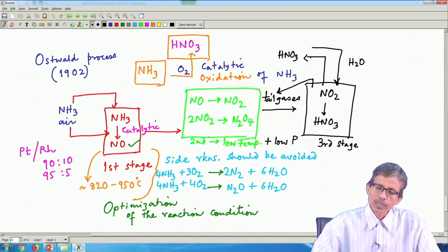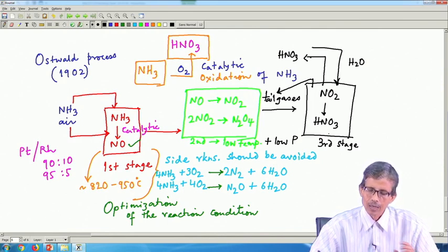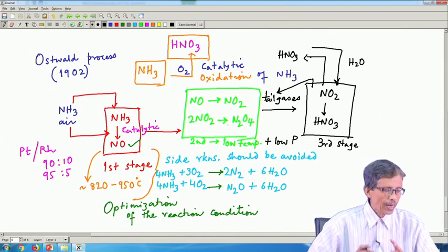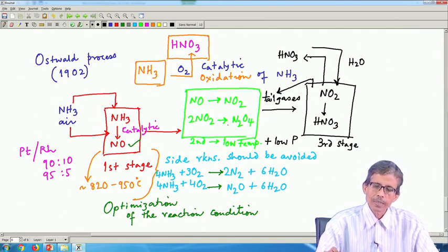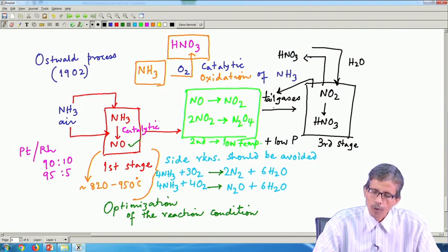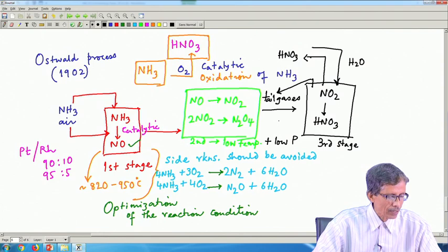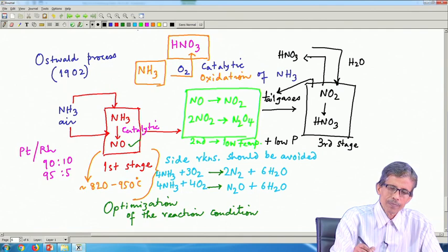So, the gases which are not converted quickly or immediately to nitric acid are still there. That means all the nitrous gases, not only your NO2, but NO can also be there because NO is your starting compound. So, NO, NO2 and N2O4, a mixture of all these gases can be there, and the formed nitric acid can be contaminated with the tail gases. So, we have to purify this nitric acid from the tail gases. The purification process is therefore a very important step of these reactions.